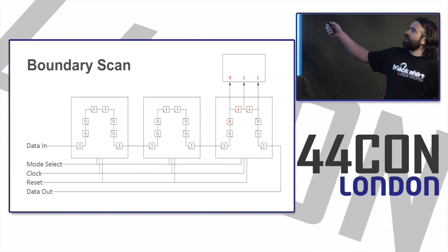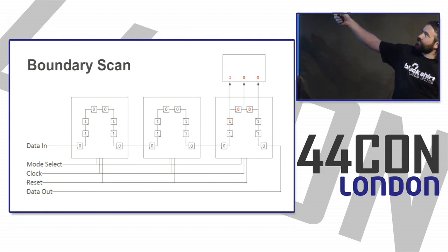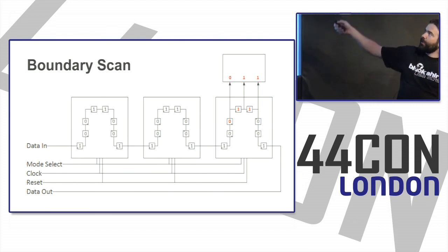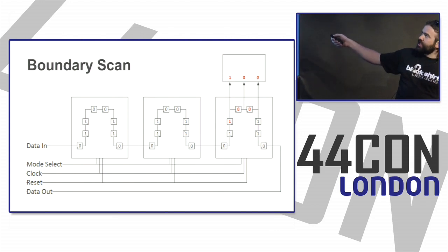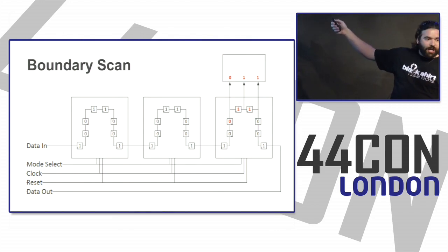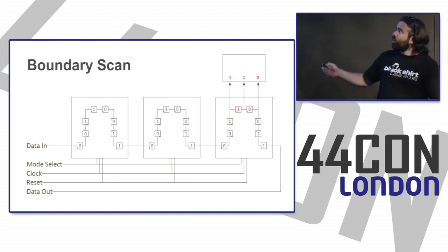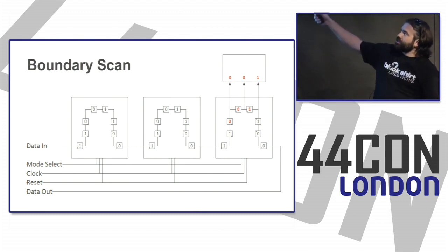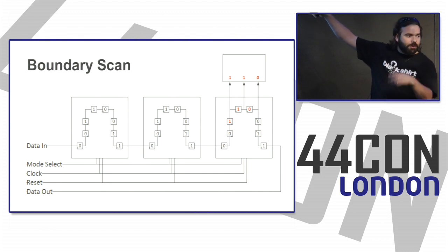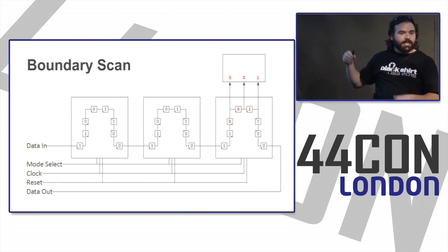And you can see right here, on our circuit board, we have a bunch of traces that go to yet another chip. By doing this, we can actually set the values that go out on those output lines, and we can either check with a logic analyzer or oscilloscope, or we could actually have another chip over here. These pins might be mapped over to this chip here, and we could be reading in at the same time. So we can see the connectivity.